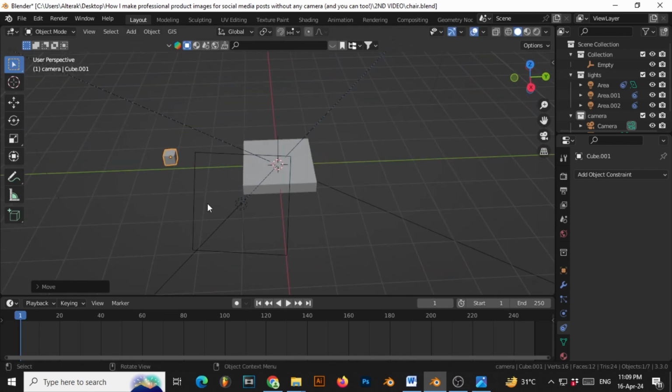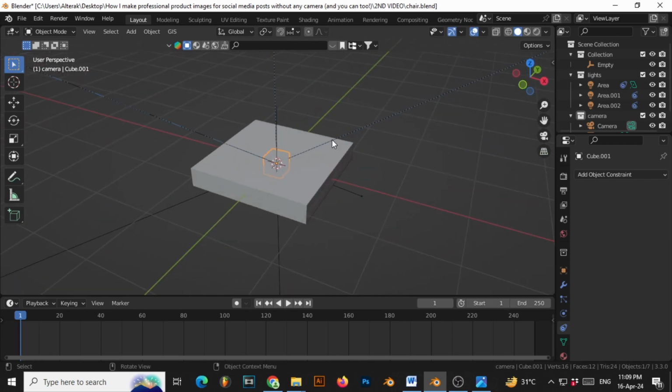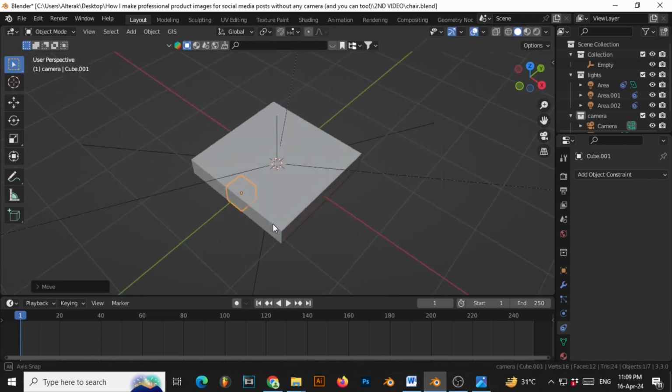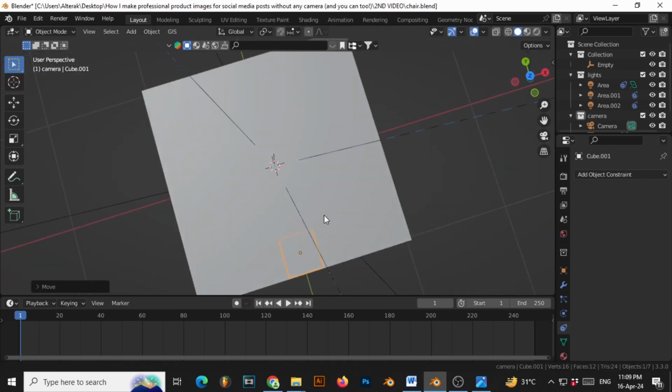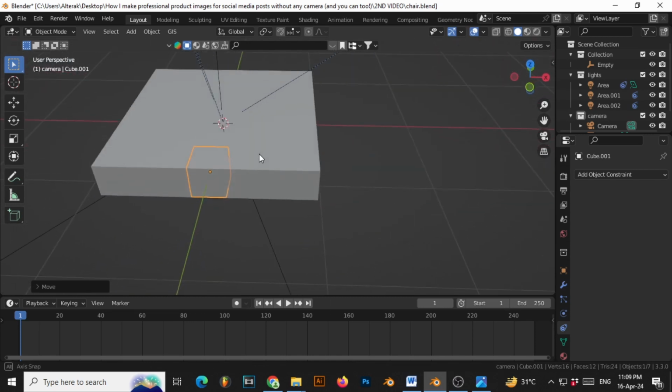But if you want to restrict the dimension where you're putting it, press G, and then again, just like we did for scaling, press X, Z, or Y. So let's just put it right about here. We're just eyeballing things, don't worry about it. You can learn all of these things later from someone else probably.